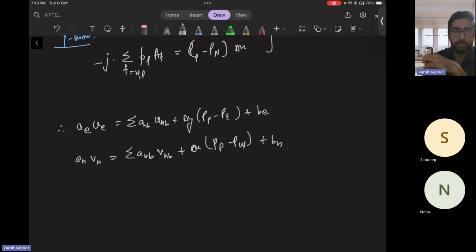So we have the discrete momentum equation and the discrete continuity equation, but still we do not have any equation for pressure. Now what about the neighboring values here, A nb and U nb, in the context of the collocated approach? Those were east, west, north, south, and so on. But because we have shifted these things, U and V neighbors are also now different.